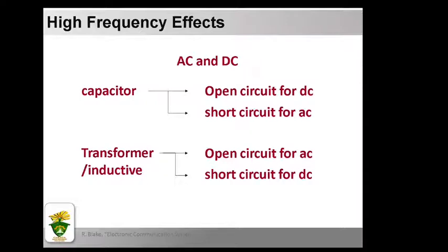Further investigation, however, especially at extremes of the amplifier frequency range, might reveal the need to consider not only inductive reactance, but also losses in the iron core of the inductor or transformer.